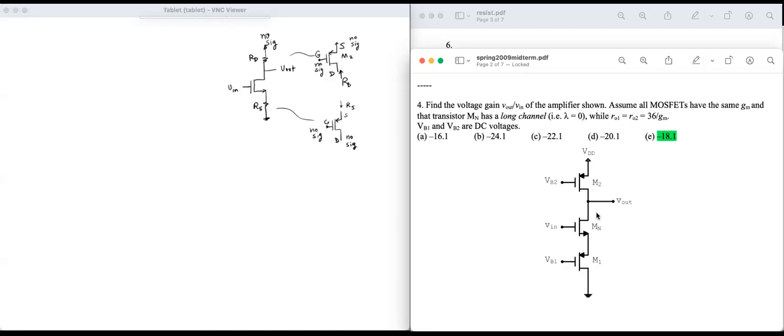And that's RS. All right. So MN is the amplifying MOSFET, and it's a common source configuration with RD and RS implemented by P MOSFETs. RD is the resistance seen looking into the drain of M2, and RS is the resistance seen looking into the source of M1.